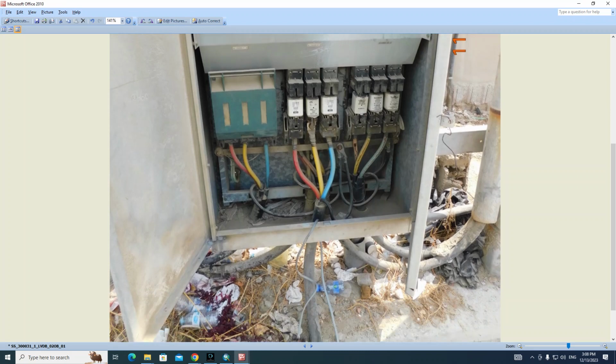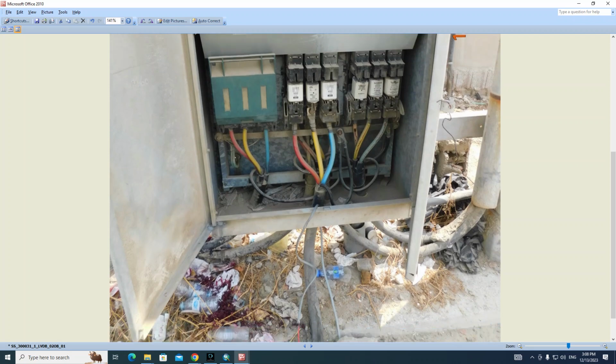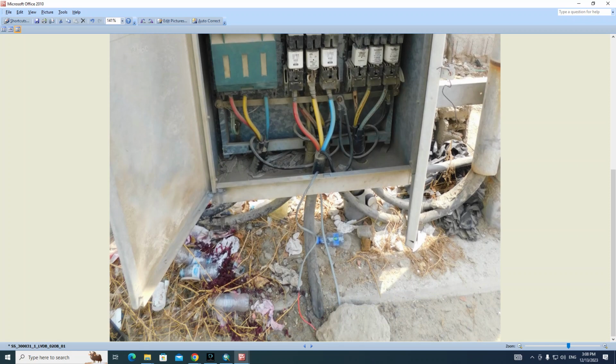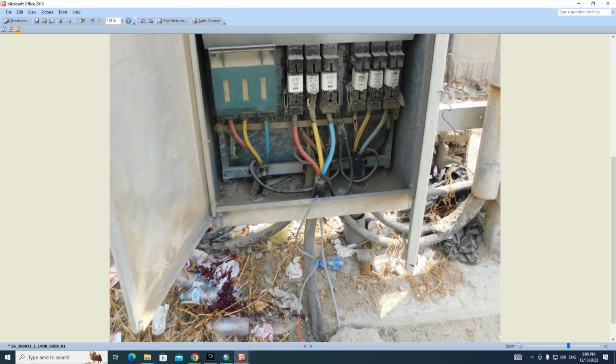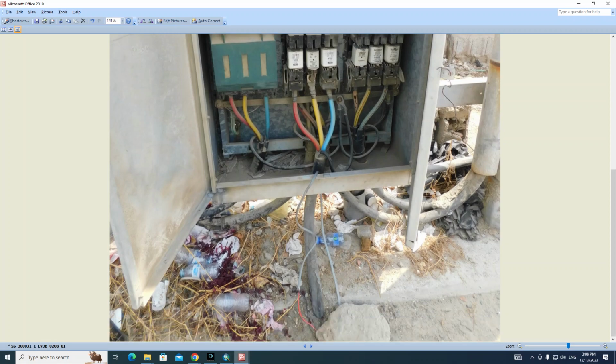Now, the second thing to identify is how many cables are going from here. There are 3. Okay, the first one, which is this one, obviously it is going underground. Okay, and we have another cable here. It is going up, and on the right we have another cable going up. So 1 cable riser and 2 LVOH cables. Okay, now we will draw this line.